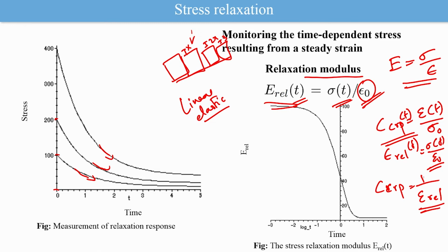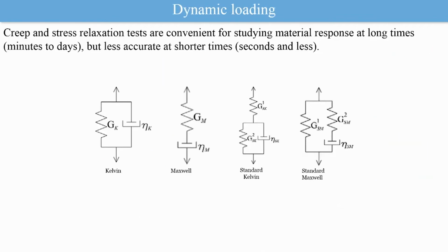They might be dimensionally same, but effect wise they are not the same. And the rate at which the relaxation happens compared to the stabilization of creep is actually faster in case of stress relaxation. So there is a difference between both, one is not the reciprocal of the other.